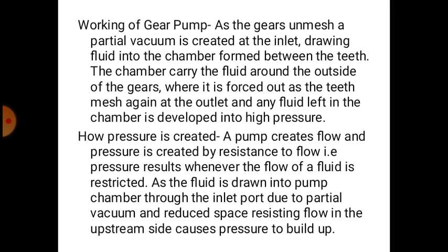Working of gear pump. As the gears unmesh, a partial vacuum is created at the inlet, drawing fluid into the chamber formed within the teeth. The chamber carries the fluid around the outside of the gears, where it is forced out as the teeth mesh again at the outlet, and any fluid left in the chamber is developed into high pressure.